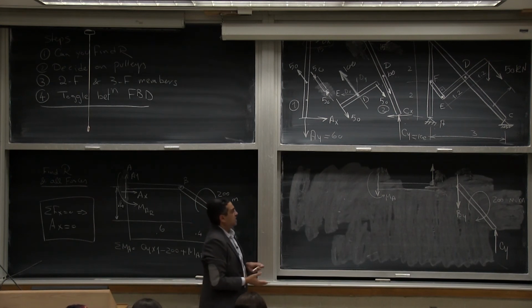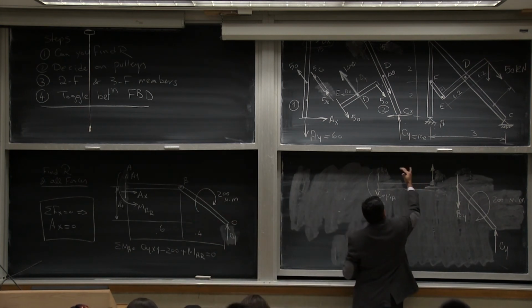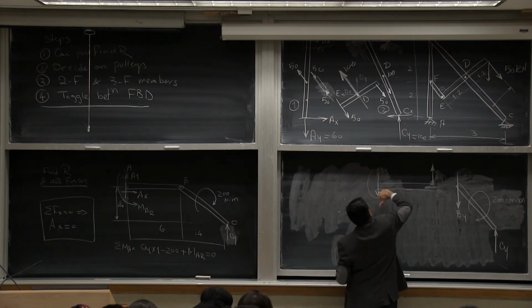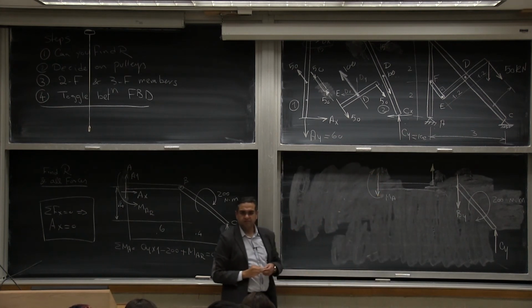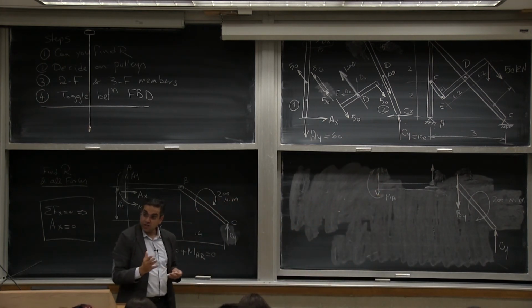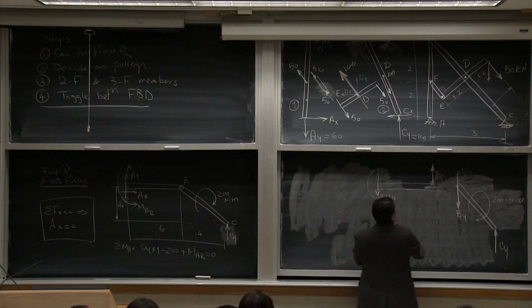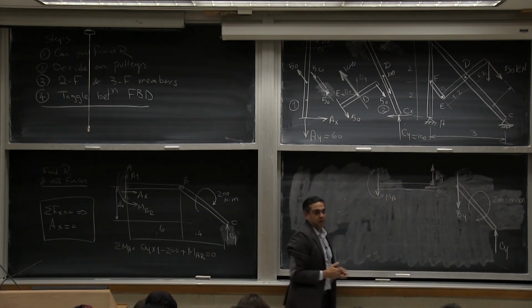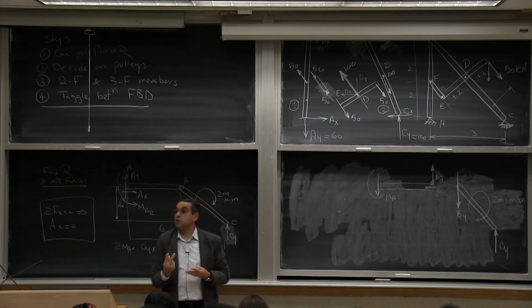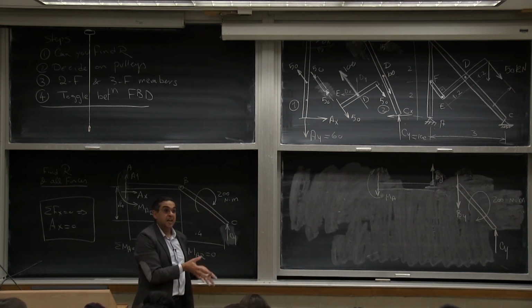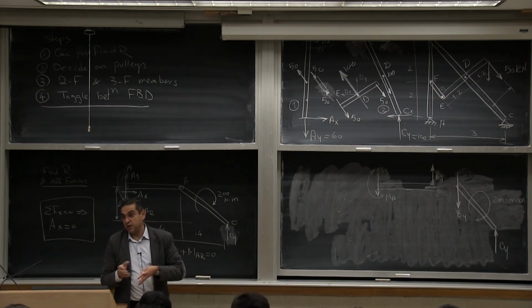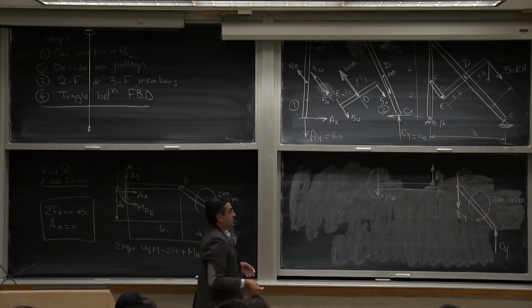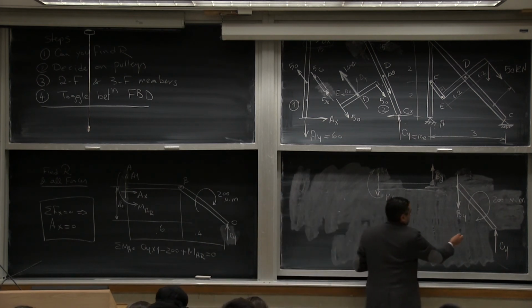Okay? And if that's the case, BY and AY are going this way, and MA is going this way, I better reverse MA. So I reach that BY is going up, AY is coming down, so their moment is going this way. This should be going this way, because AB is subject to two couples, one that is concentrated at A and one that is created by BY and AY. And now I can solve for free body diagram 1.